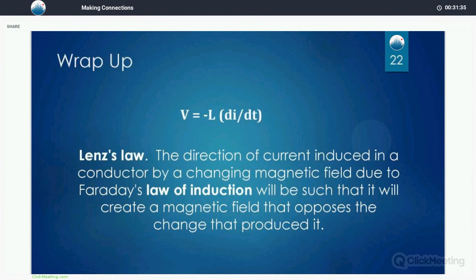The real point here that we wish to make today is this simple formula. The amount of voltage that you get induced through a change in current is proportional to the inductance, proportional to the current, and inversely proportional to the time. Since we really don't want to change di, dt, we probably want that really fast in our applications. What we need to change is L. Let's get the inductance out of the picture. We will not have so much reverse voltage or reverse EMF generated, and it will not affect our waveform.